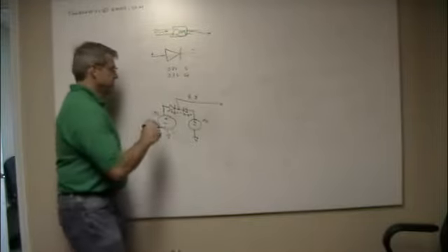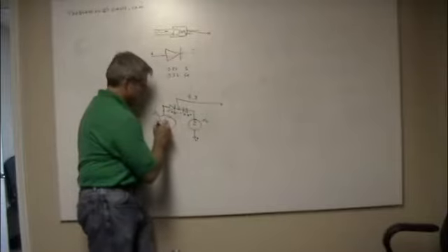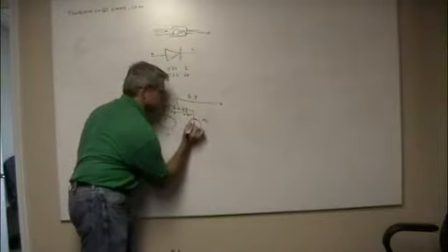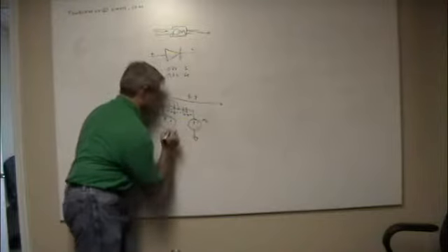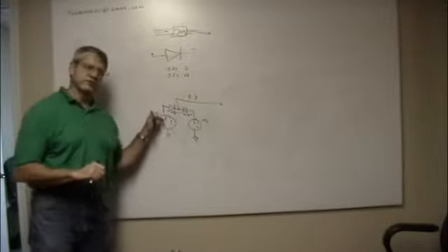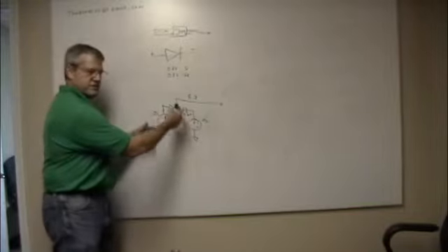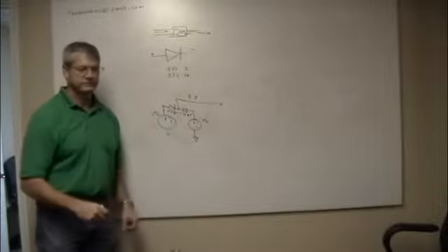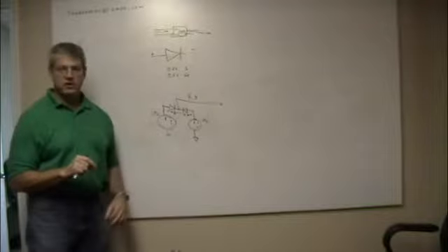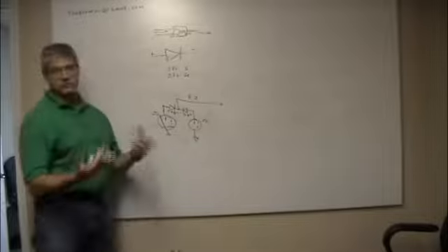So I get 4.3 volts out there, but what happens is I draw current. Remember, these things are ideal, right? So the truth is, there's a little bit of a resistor in there. As I start drawing more current from this guy, his voltage will start to droop a little bit. And there comes a point where they balance each other out and they're both supplying current. Unless there are huge differences between them. If they're really close, then I can get more current. Or I've got redundancy. If one of them decides to die, I've still got this one feeding. And that's what I use them for mostly, is redundancy.